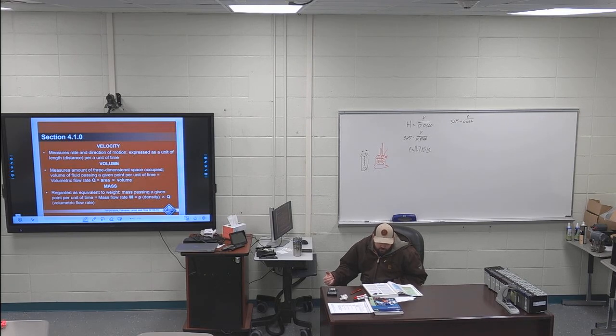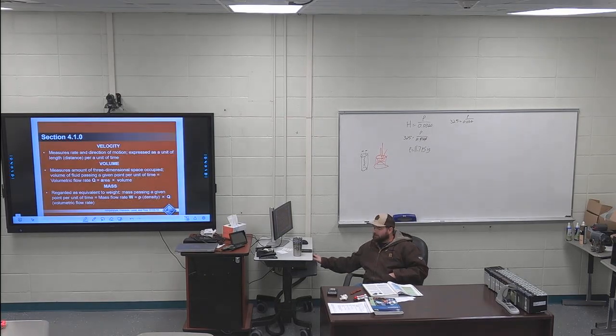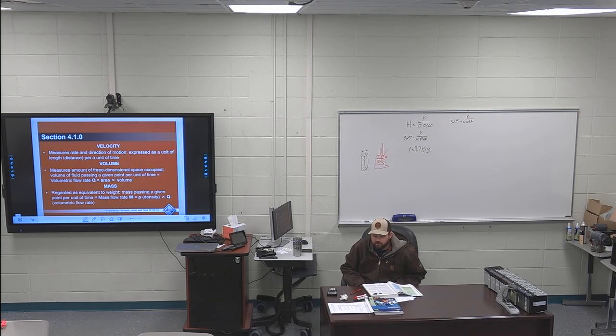Flow measure units. Before going to that, I don't have a picture. Picture in the top right of the page, you can have flow straighteners. So you can actually put those inside of a pipe and then get laminar flow on the back side of it. So they help. So for a lot of instruments, you either have to have a certain distance of pipe before the instruments, or you have to put a flow straightener in it. A lot of times it's like 6 or 8 feet of straight pipe with no turns before your instrument, or you could have 3 feet of pipe with a flow straightener and they'll work the same.